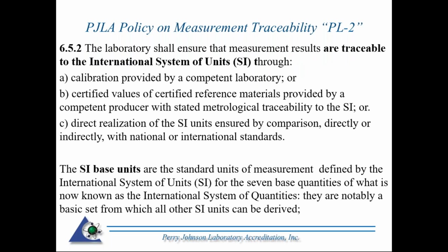We keep hearing that term SI units, and right out of the standard, the laboratory shall ensure that measurements are traceable to the International System of Units, SI, through calibration provided by a competent lab, or if it's a reference material, certified values of certified reference materials provided by competent producers with stated metrological traceability to the SI, or, and this comes right out of 17025, direct realization of the SI units ensured by comparison directly or indirectly with national or international standards.